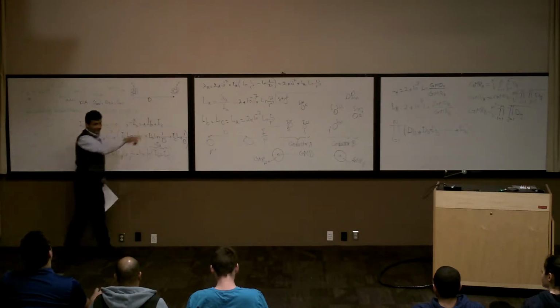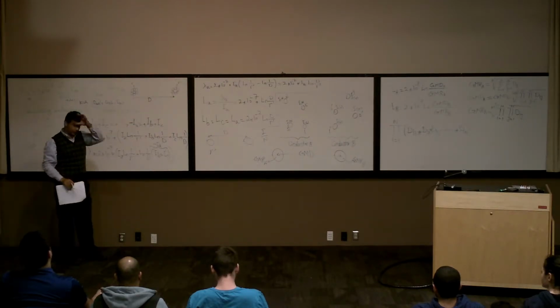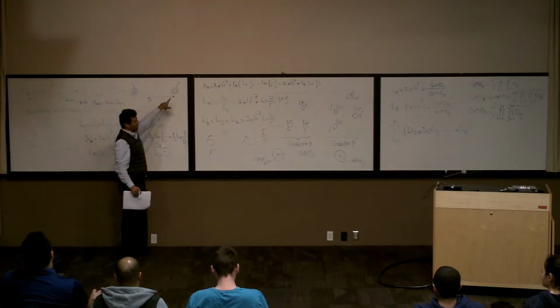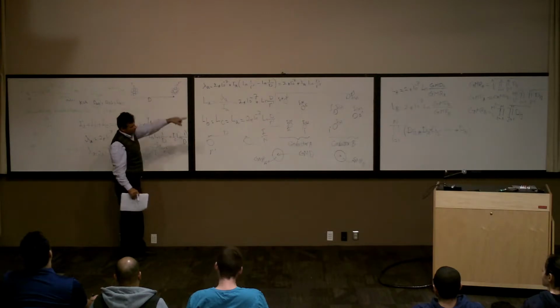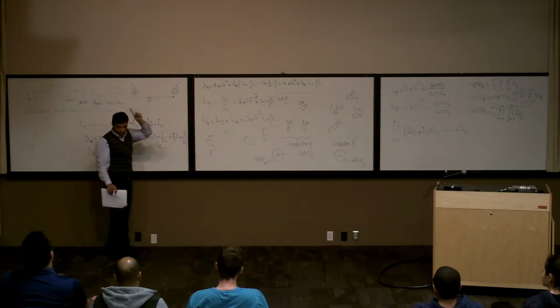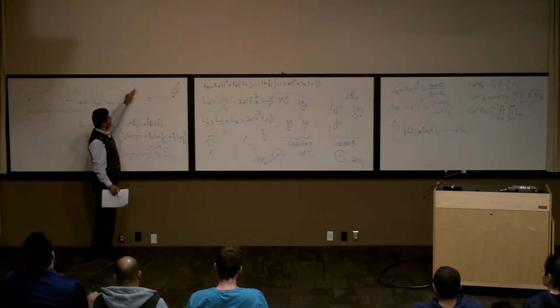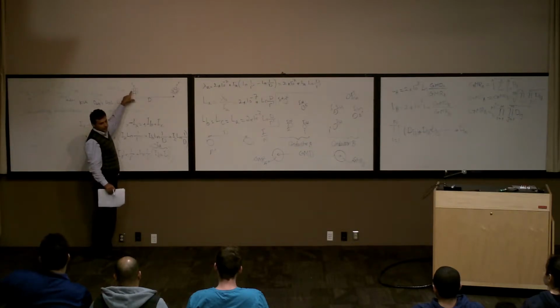If you are going to go with that equation, we have 7 conductors here, and we have 7 conductors here. For the GMR, if I'm going to calculate the total GMR, it's going to be this one, this one, this one, this one, this one, all together. You treat it that way and you find the GMR.